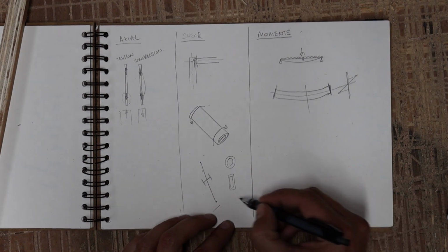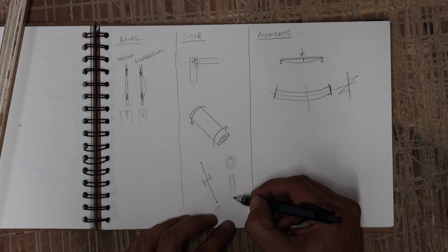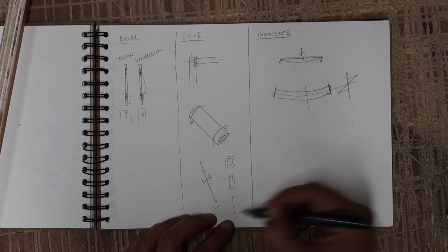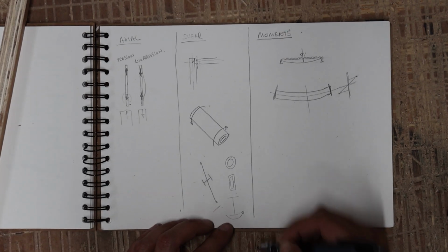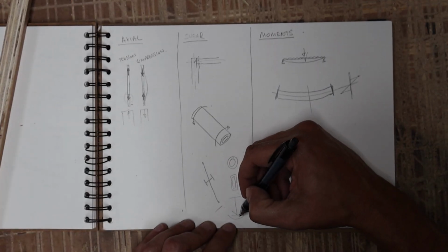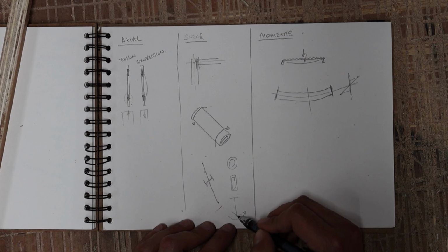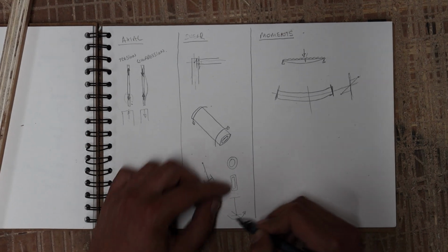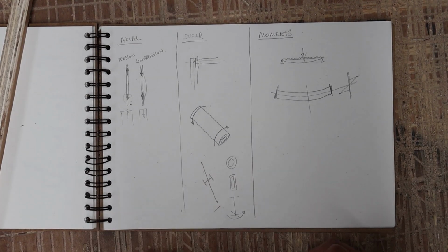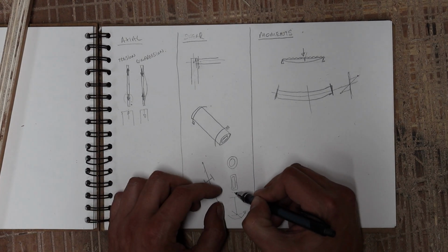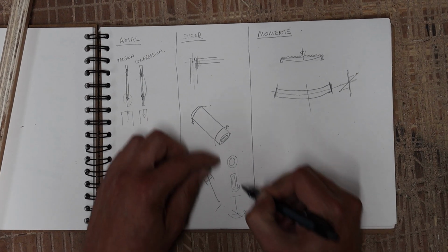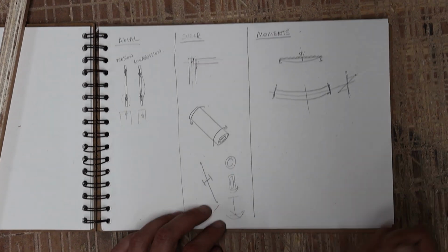And one other reason why we generally do that: if we go for a standard I-beam and we try to apply a torsion on the bottom flange, for example, then what will generally happen is that flange will just deflect. It will just bend around this point here. All of that torsion won't get transferred into all of the beam. So we generally tend to use hollow sections, because if you apply a torsion here, it really transfers it around. It's a really good shape.